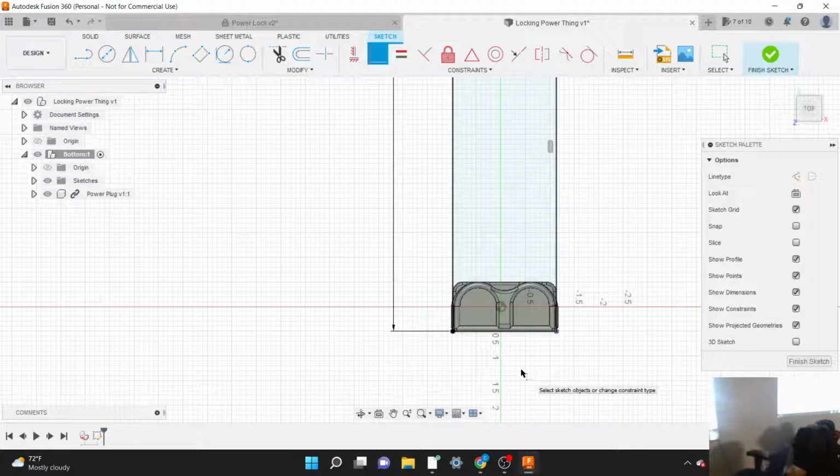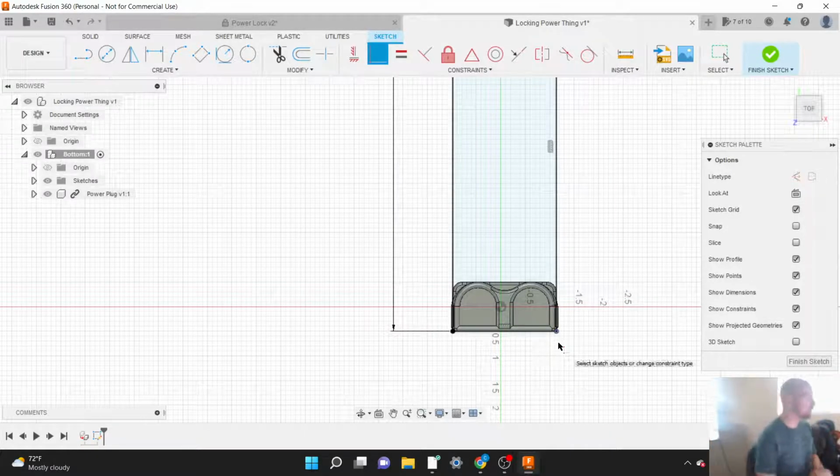So if you click on that dimension, you may have to hit escape or something like that. And then you click on that dimension. Instead of double clicking, just a single click. So you may have to hit escape again. And then, don't double click, just single click, and then hit delete. There we go. Now it should let you constrain that. Coincident. Dot. Line. Okay, thank you, sir.